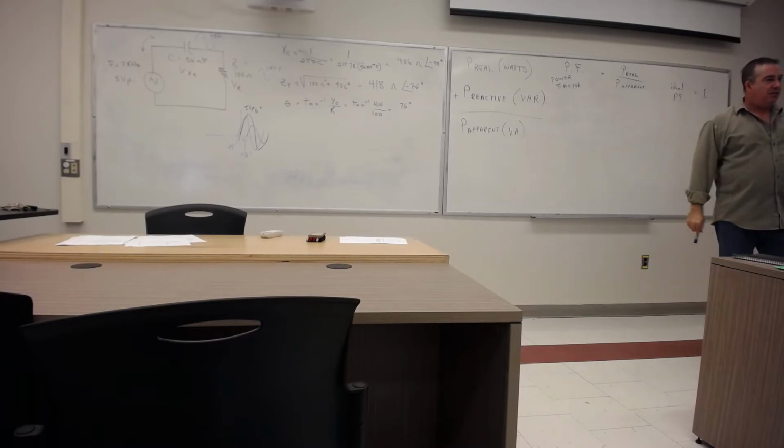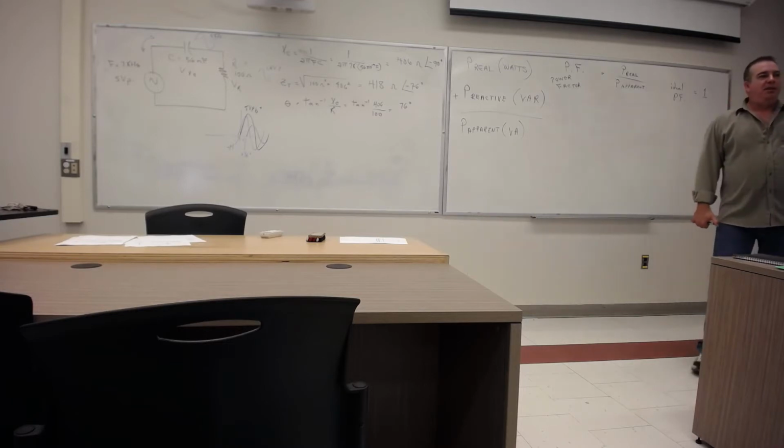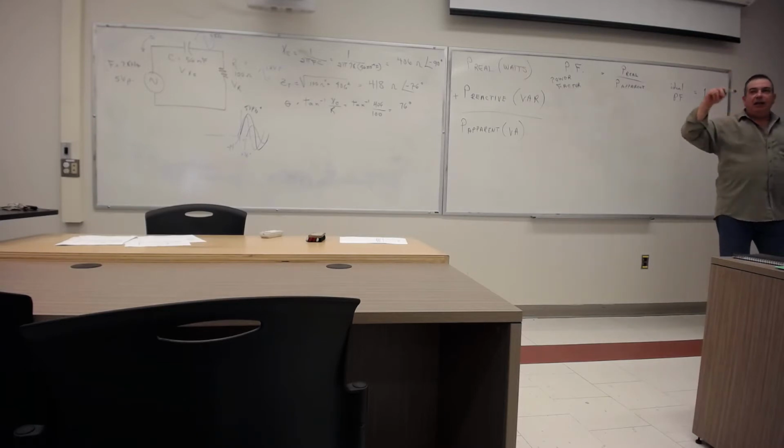It's wasted. If you go look up Ontario Hydro's site or BC Hydro or anywhere like that, they actually have a table that says if your power factor in your factory is less than 90%, there's a 2% surcharge. If it's less than 80%, 4%. They charge you if your power factor is poor and a lot of power is being bounced back to them.